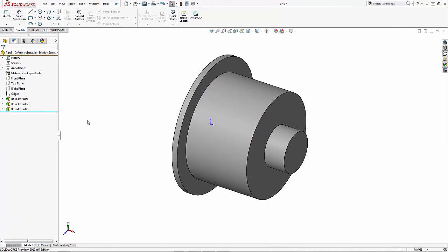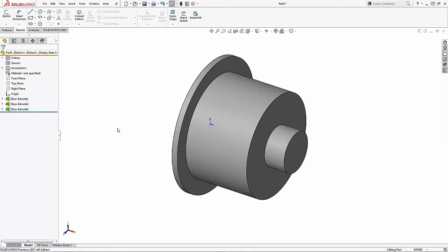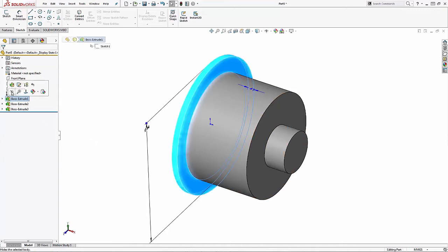So as mentioned earlier, with the layer cake method, we have 3 unique part features, as I'm highlighting them out accordingly. And the nice thing about this is that from a simplicity standpoint, it's very easy to create, and it's also very easy to edit. So if we wanted to change maybe the overall diameter or maybe the extrusion length, it's just a matter of editing the part feature. Whether we access it here, we can go to Edit Feature here.